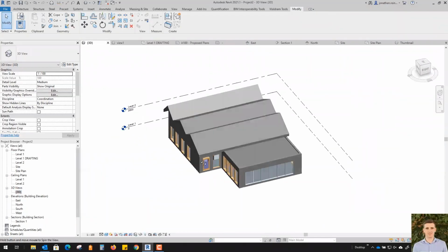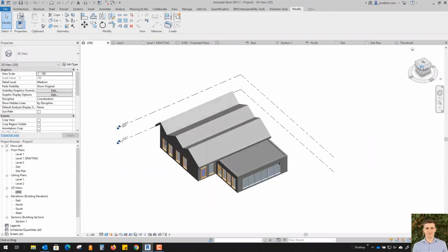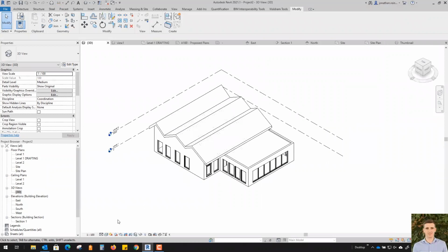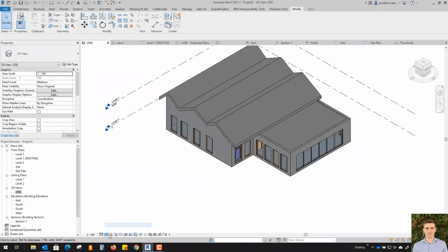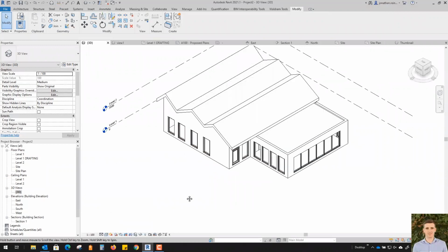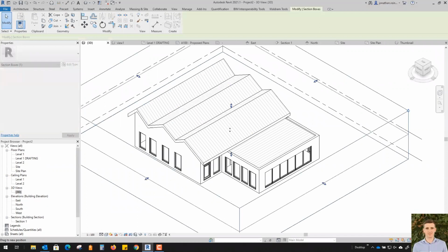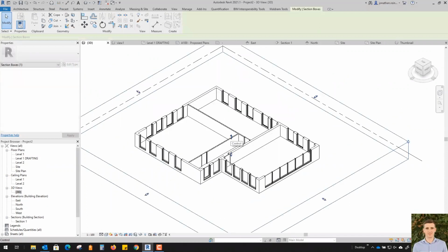What we're going to do now is place some 3D views on sheets. We're going to cut the floor plan using the section box and place that on a sheet. Then we're also going to cut the roof plan in 3D to show it on top of the floor plan. It looks like a nice stacked 3D view, both of the floor plan and the 3D of the roof.